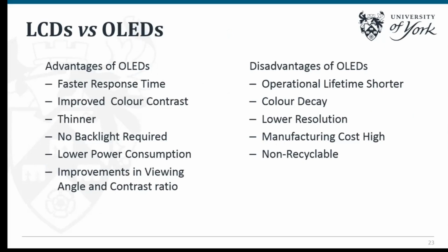The reason why they will is because they have certain advantages over LCDs. They have a faster response time and improved color contrast because it's a directly emitting layer instead of being a backlight and two polarizers. They're also thinner, partly because they don't require a backlight or polarizers, which makes them lighter. They also have a lower power consumption than LCDs and improvements in viewing angle and the contrast ratio. The reason why they have yet to actually fully compete with LCDs is because of several major issues.